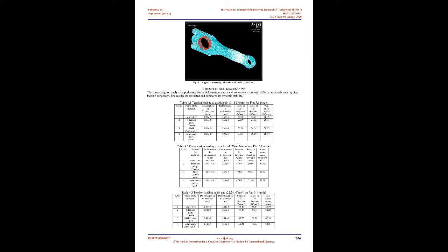1. Introduction. The crankshaft conrod mechanism transforms reciprocating motion to rotational motion. The conrod connects the piston to the crankshaft to transfer combustion pressure to the crank pin. There are bearing portions at both ends. The piston side is called the small end, and the crankshaft side, the big end.